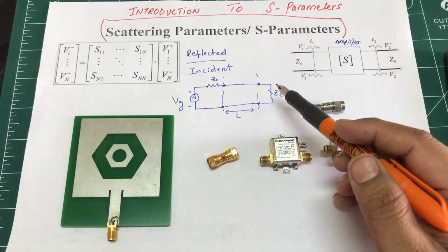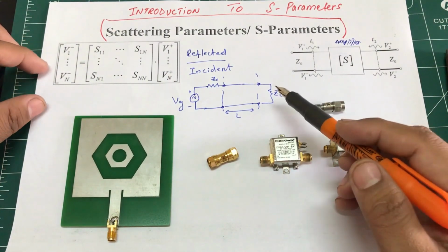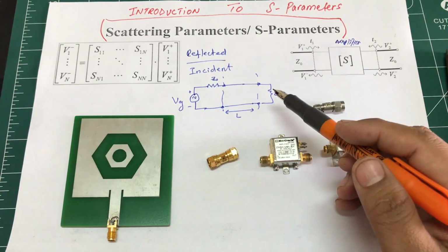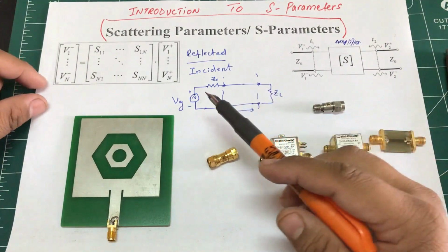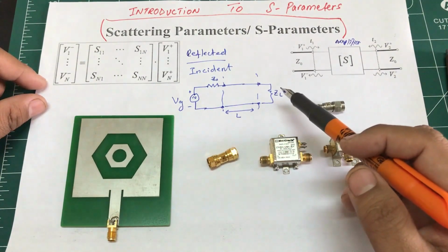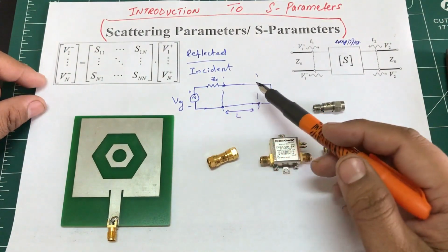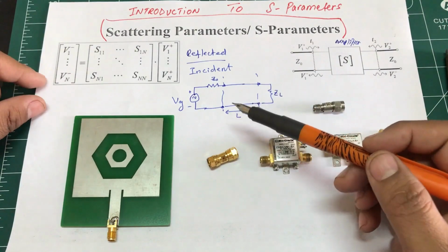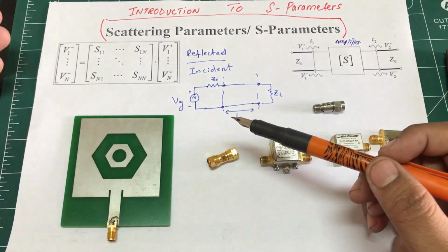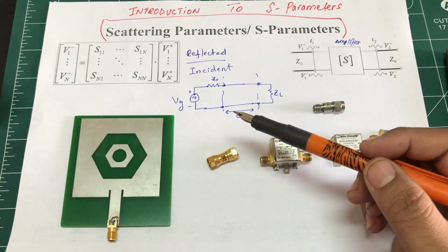At lower frequencies we call that maximum power transfer, but at higher frequencies we are actually looking at it in terms of reflected voltage. So let's say you supply 10 volts, and due to mismatch of the load you receive 9 volts. Where has that 1 volt gone? That 1 volt is being reflected back into my system. At lower frequencies we don't care, but at higher frequencies that is quite worrying to us, and we need to learn how to solve this.